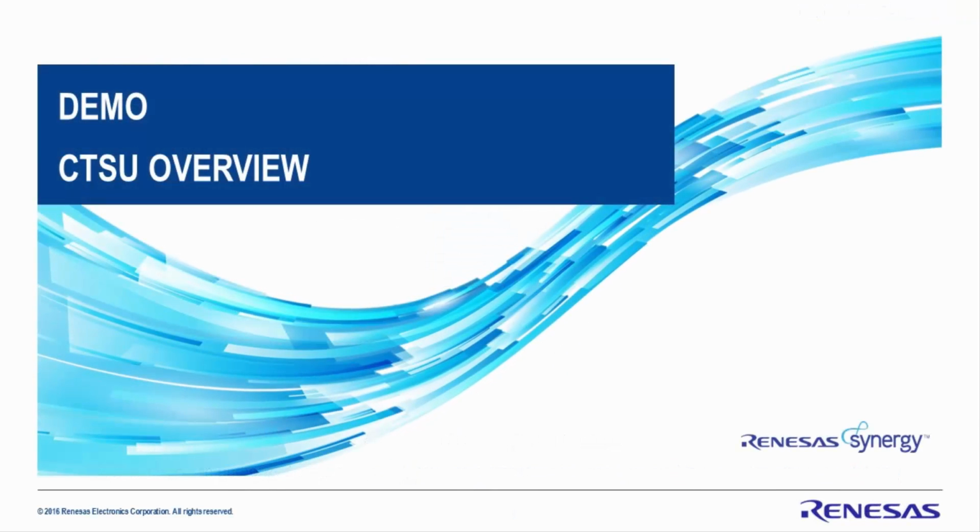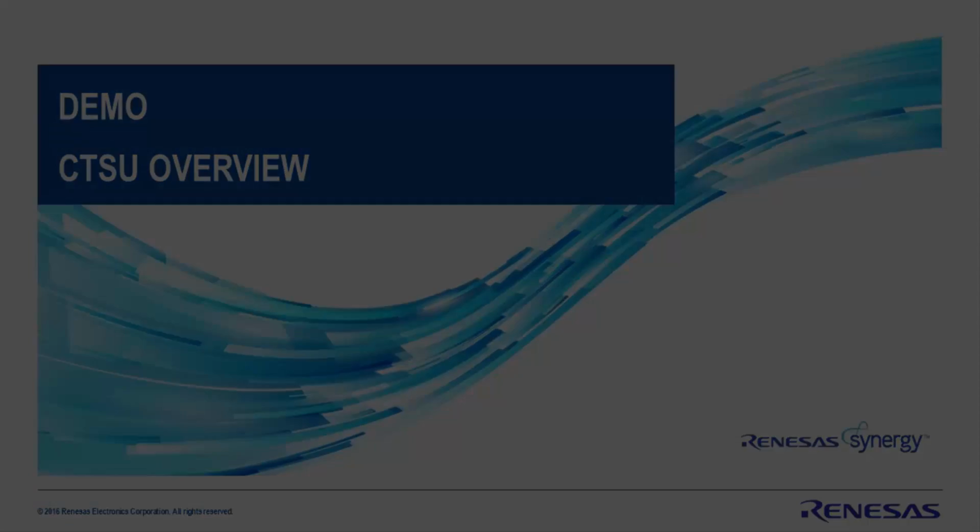The Capacitive Touch Sensing Unit, CTSU, measures the electrostatic capacitance of a touch sensor. Changes in electrostatic capacitance are determined by software that enables the CTSU to detect whether a finger is in contact with a touch sensor. Electrostatic capacitance is detected by the self-capacitance and mutual capacitance methods. This application note uses the self-capacitance single scan mode for the slider and button functionality.